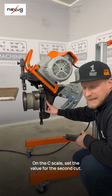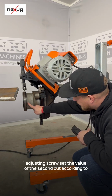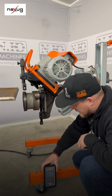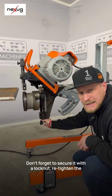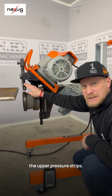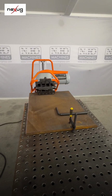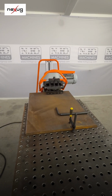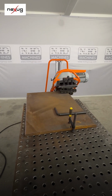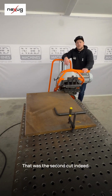On the C scale, set the value for the second cut. Loosen the center bolt of the main roller, and with the adjusting screw, set the value of the second cut according to the cutting plan calculation. Don't forget to secure it with a lock nut, retighten the center bolt of the main roller, and adjust the position of the upper pressure strips. That was the second cut indeed.